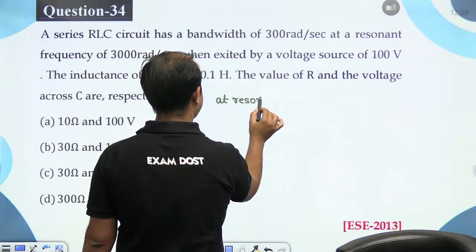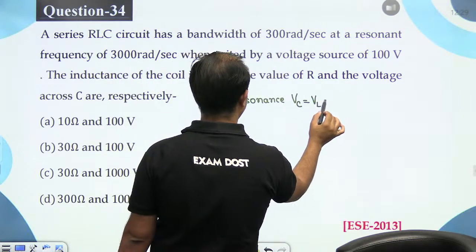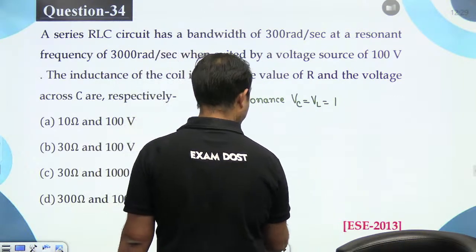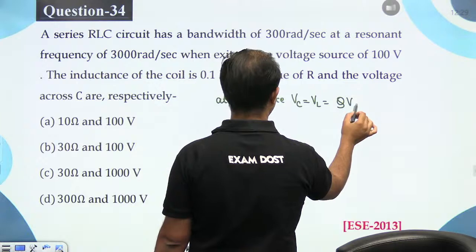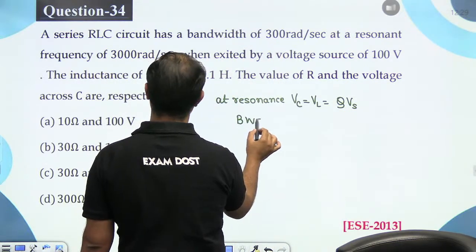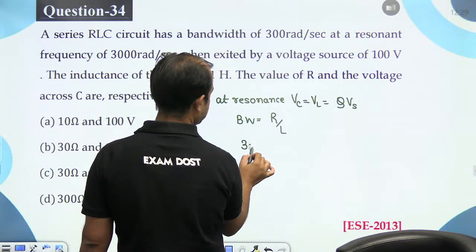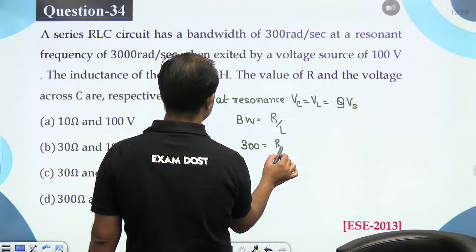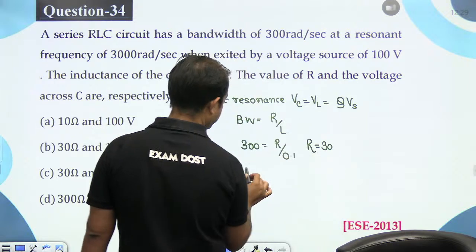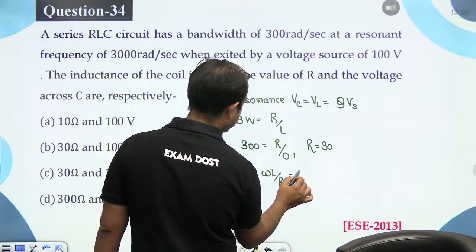At resonance, VC is equal to VL, equal to Q times VS. Bandwidth is R by L. Now quality factor is omega L by R.